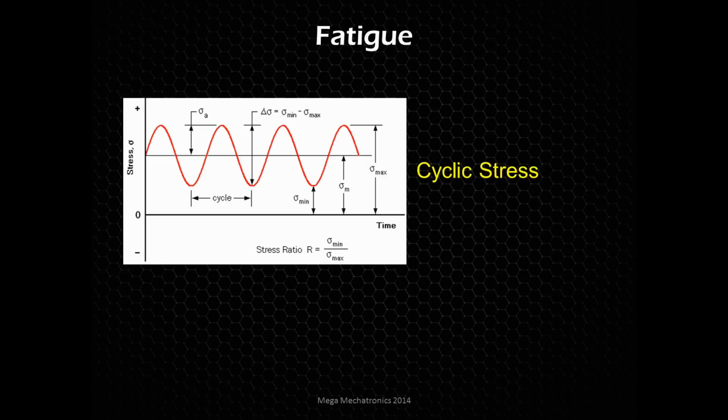So in this particular example, very nice, even stress, and you see it's being stressed on the tension side. So the space between the zero and the minimum of those valleys is a pre-tension, because it's not reaching zero, or it's not going into compression. So here it's just being stressed more and then stressed a little less on the tension side.